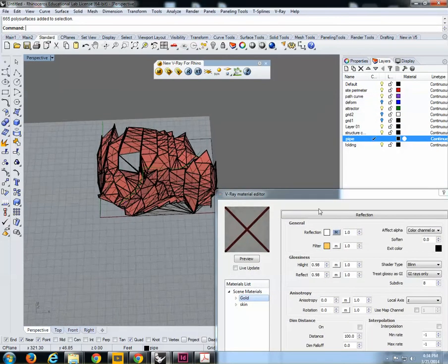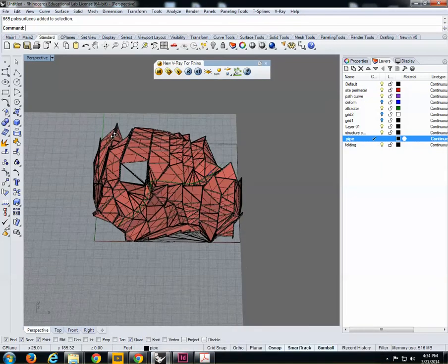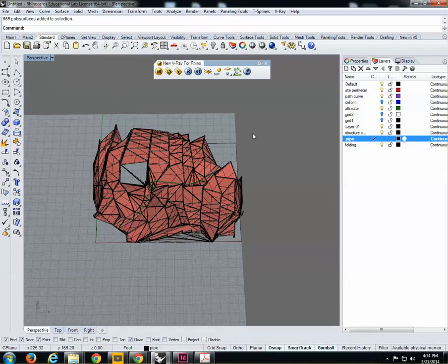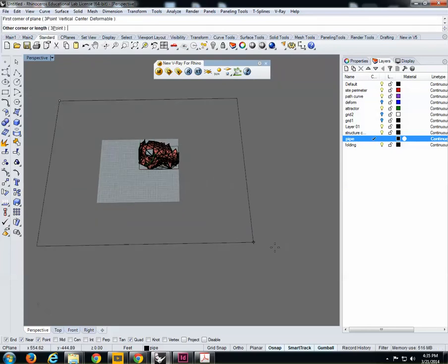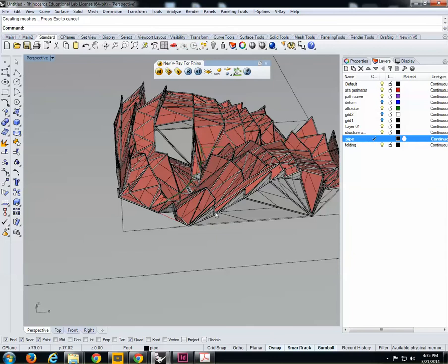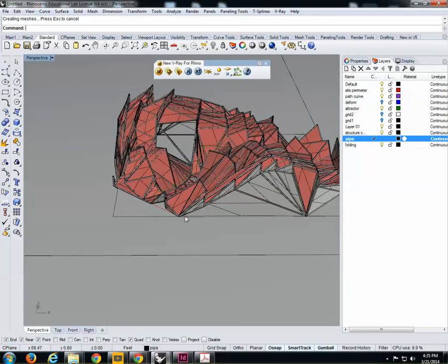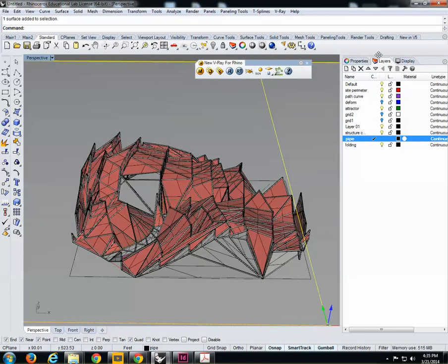Two more things we have said when it comes to rendering. As soon as you are done with the materials and the output, you want a light and also you want a big base to act as your ground. The big base is going to be generated through the command plane. So all you need to do is to draw a huge plane. So this composition will cast some shadows down here. Now, because we're running late, I'm not going to work more here. You guys know that you can add also light and also another material for the base.